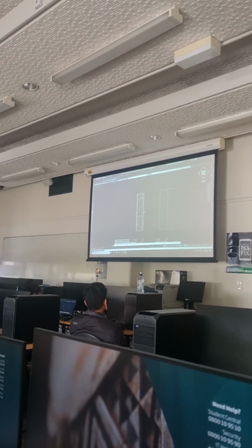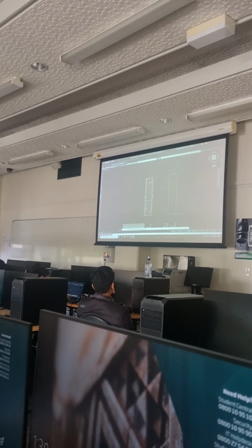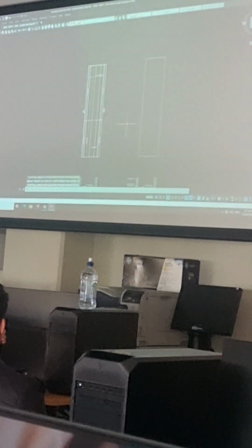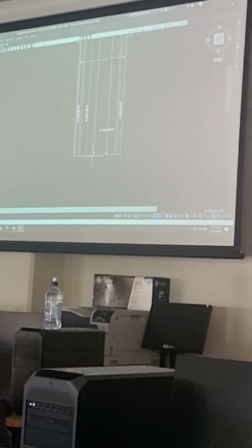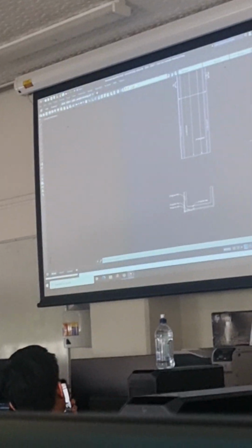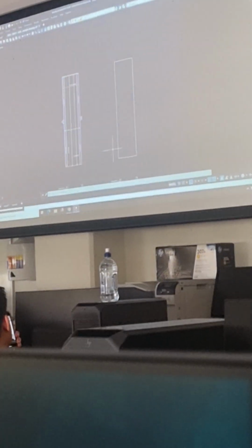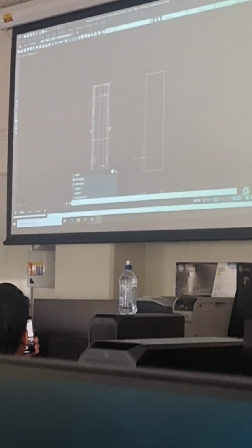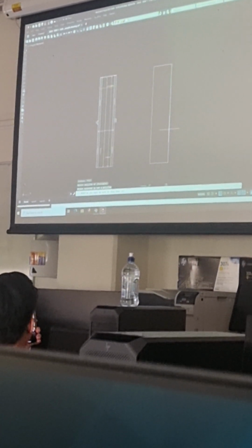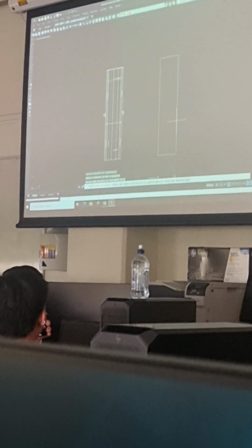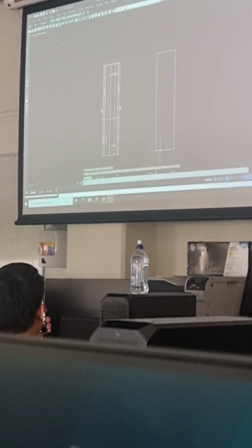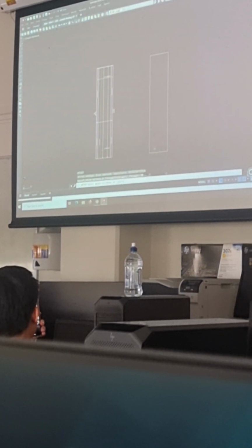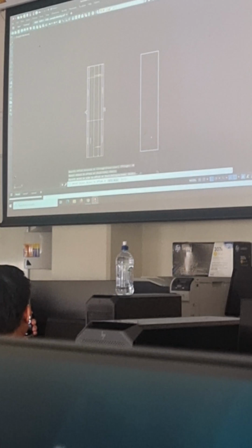I think I can see. Can you just forward that? There we are. Okay, now I know that on this particular case, looking down on it, the cover is, I think, 50, might be 40 actually. So I'm going to go P-edit and I'll turn this into a, click on here and go yes, J for join, and once again we'll grab all that and we've made it into a P-line. So if I offset that by 40, which I'm pretty sure the cover was, I've now got a cover line.